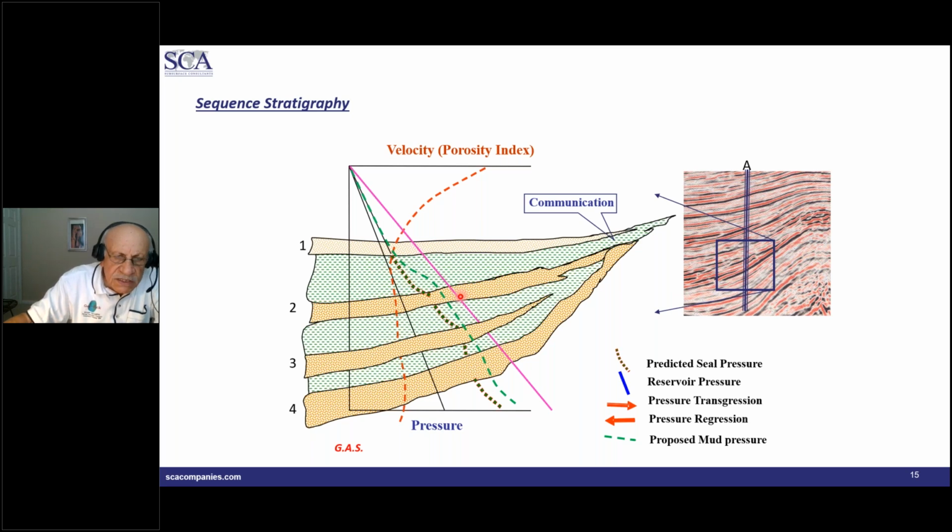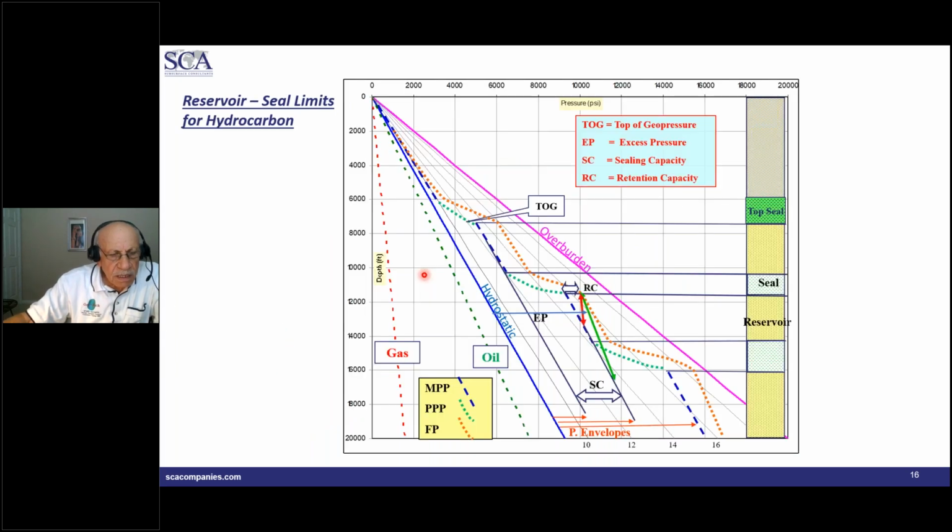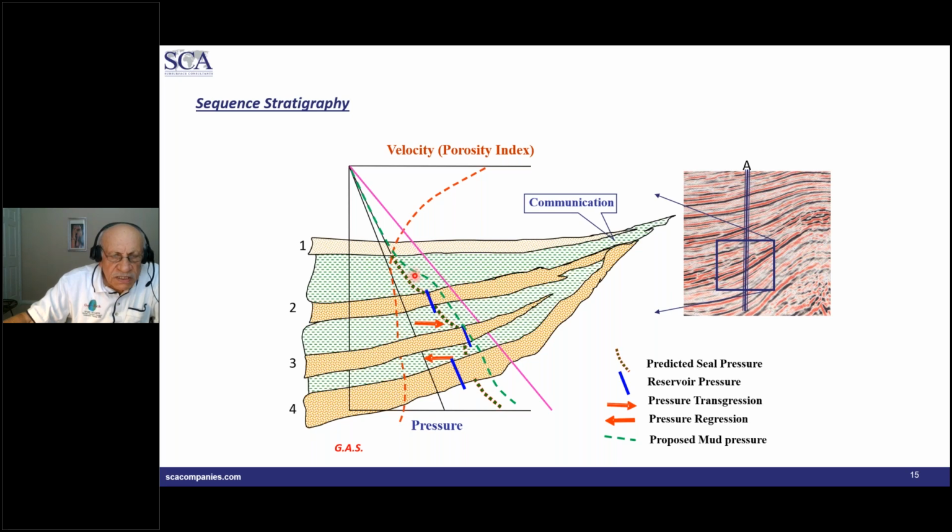And then I give this to the drilling engineer, and say, well, here is our predicted pore pressure, add half a pound, and here is our mud weight. So they designed the mud weight. When they designed the mud weight and everything is nice, and we start drilling the well, we might receive a hard kick here. And over here, we might receive a loss of circulation.